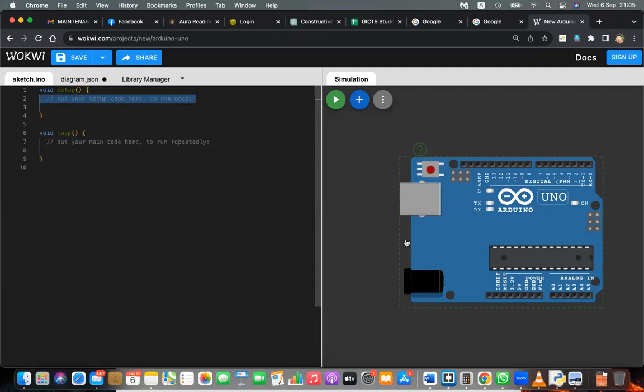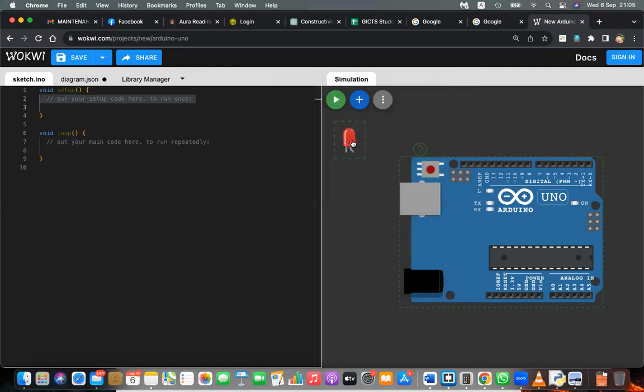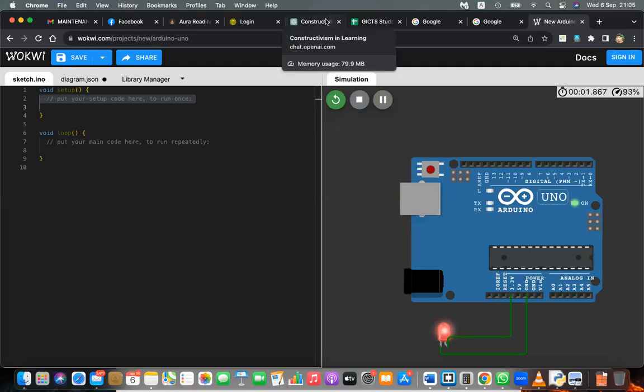Okay, very first thing, you can test this with an LED. You can get an LED and just connect the LED to the 3.3 volt pin, and the other pin to the ground pin, and check whether this is working. This is a very simple activity. Other pin, please ground it and check whether this is working when you play this. Simplest activity, because we are using existing power. Okay, please do it now.